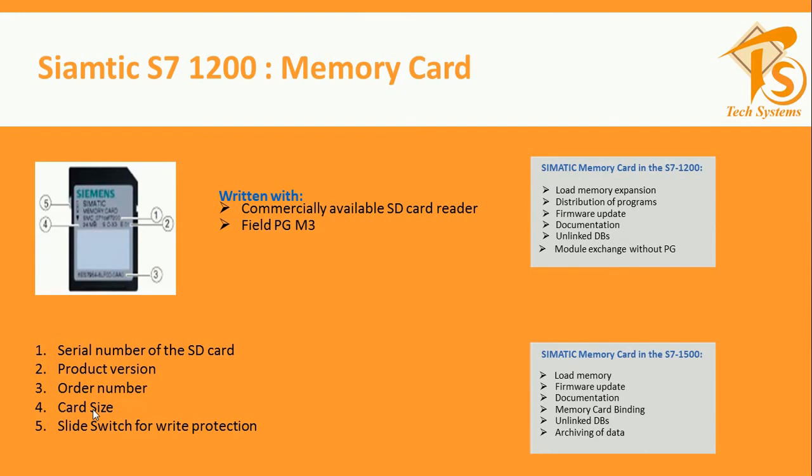So if another PLC is working in the same environment, but some problem occurs and you need to download again, in this case you need one laptop and software, and the download process is required. But if you have the memory card, in this case you skip all these steps, directly insert this memory card in the 1200 series PLC, switch the power off and power on. Automatically all the data of the memory card is transferred to your PLC program memory. So it is a very unique feature and it's very useful.